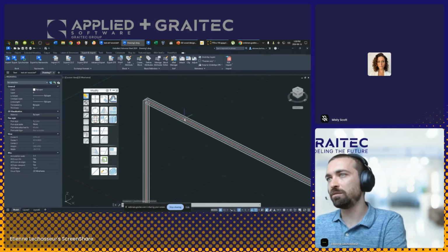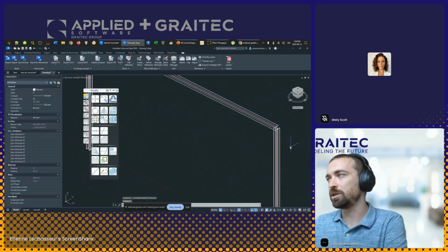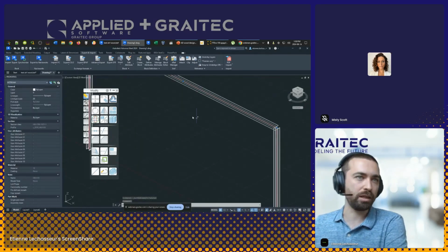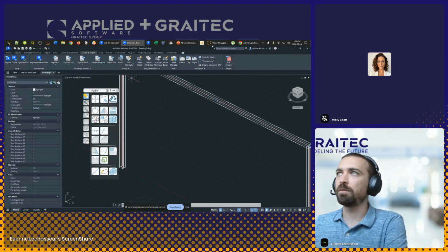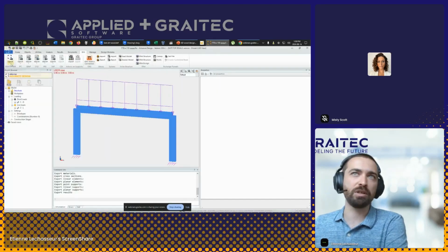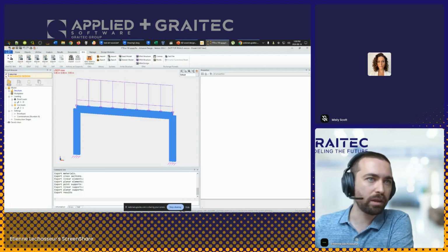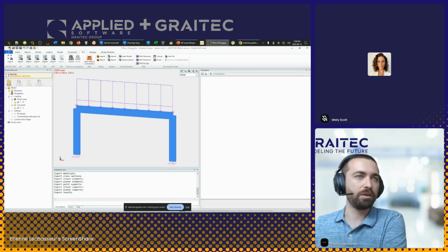Now I just assigned a random steel one, but as you can see, it really transferred as a structural element, not just a solid. But generally, I would say the best transfers would be with Revit. Advanced Steel works really, really well, especially for steel structures. For wood, Advanced Steel doesn't have the libraries yet. In any case, it would really depend on your software.